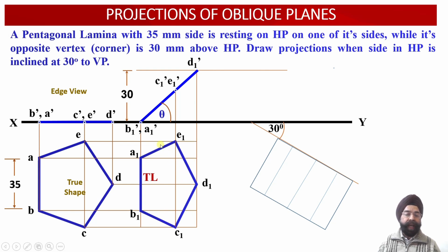So with respect to either this edge or this edge over here, you can see the 3 edges we have marked, and the same distances we have taken from the previous plan projection view. Now another thing we need to know is the location of points E1 and C1. If we are able to obtain either this distance or this distance, accordingly you can mark this distance over here or mark this distance from this position. So again the location of C and E will be located over here.